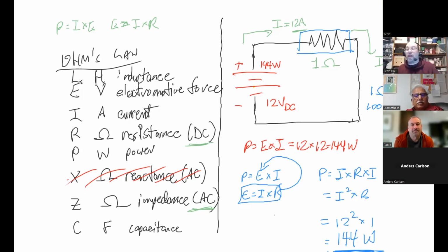And in some cases, it would actually happen quite quickly. I've done that myself, where you have a resistor that basically gets white hot and then turns into a pile of ash very, very quickly. I have actually occasionally seen a short circuit put 100-something watts through a resistor that was rated at 1 ohm at 1 watt. What do you think happens to that resistor? Wow, it would blow up. Well, again, it gets really hot really fast. I've seen one actually turn bright white and go a little puff of flame and then nothing left but char, black powder.